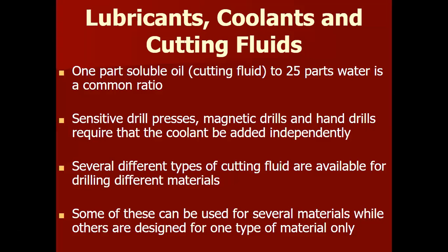and lubricants and cutting fluids. 1 part soluble oil cutting fluid to 25 parts water is a common ratio. What this is, when we got metal on metal, that's a lot of friction, a lot of heat, especially if you're cutting steel with steel.